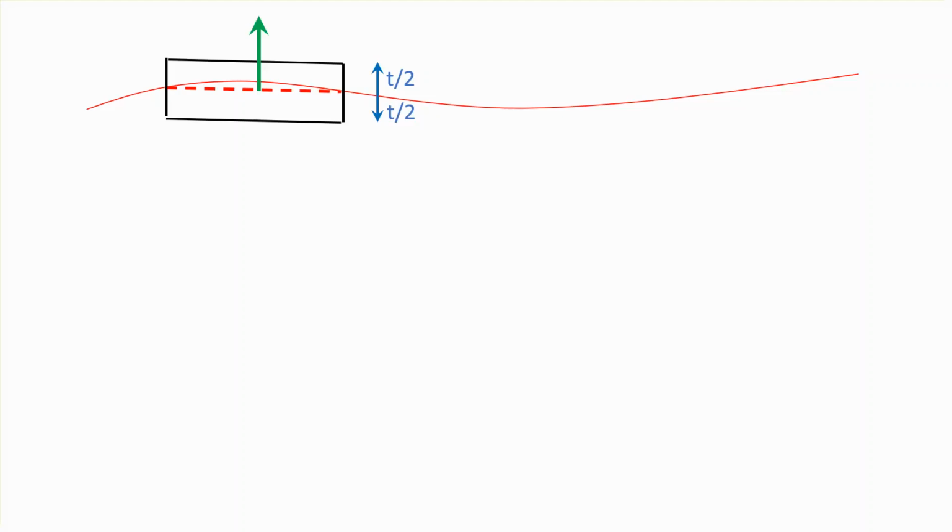That is the middle plane. Half of it goes up, half of it goes down. So this makes sense if the surface that's given to you is the middle surface. And in that case, you don't have to do anything special. There is no offset. Offset is none.